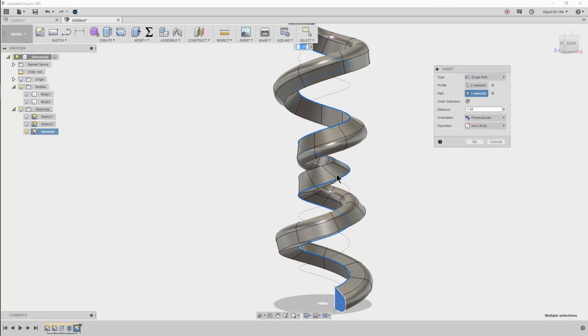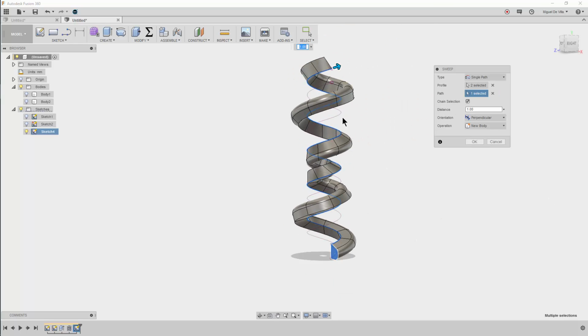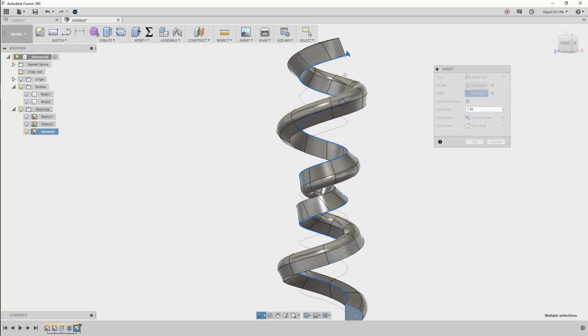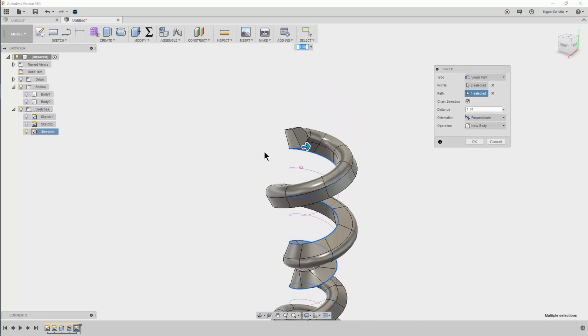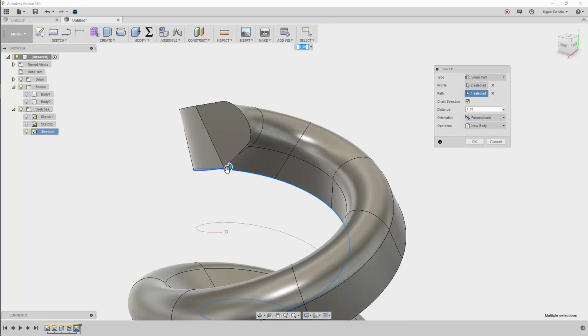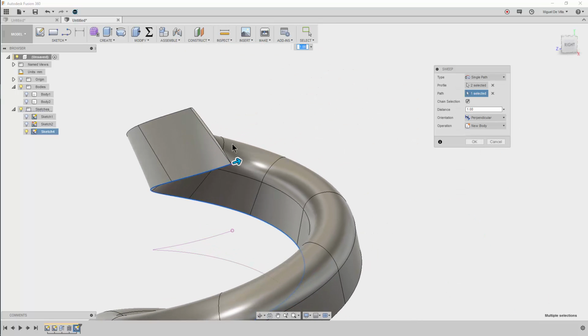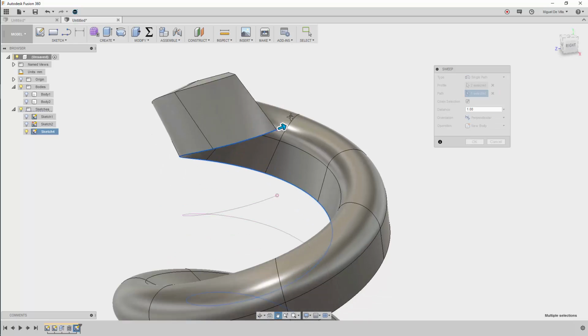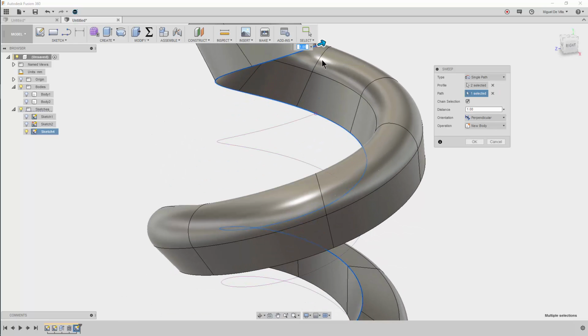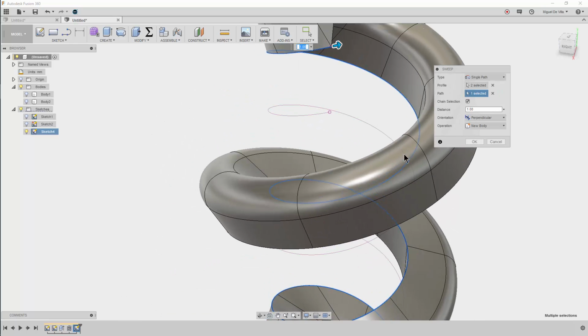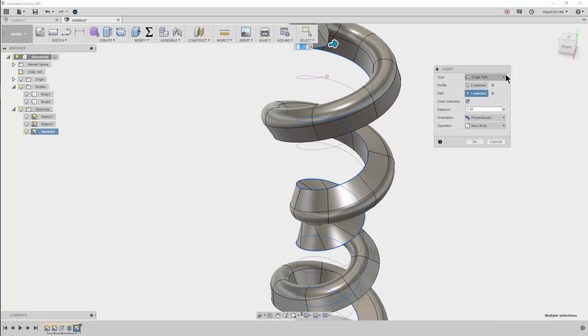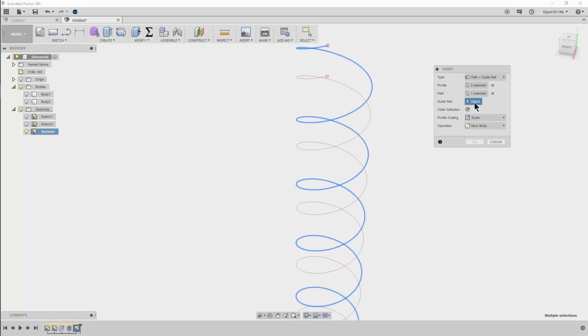And you'll notice, yeah, it completes, but it does this weird twisty thing. And that's odd, because it should be always projecting off of the line, and it is. It actually is. However, while it is projecting, it is also rotating about the line we specified, because why can't it? There's no boundary condition or constraint to say that it shouldn't. This is what the secondary input is, the guide rail.